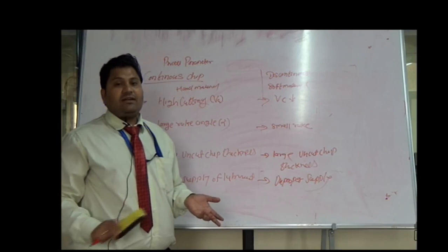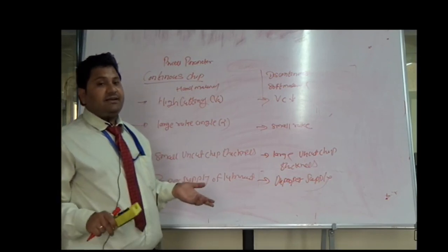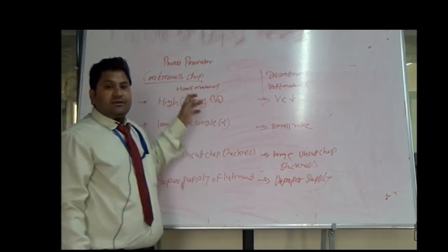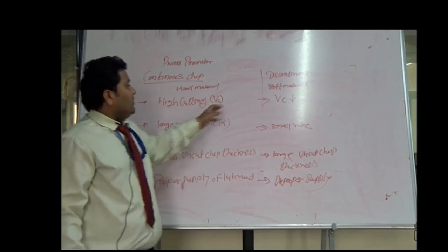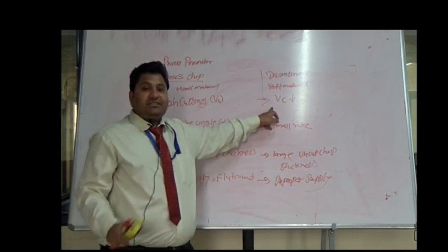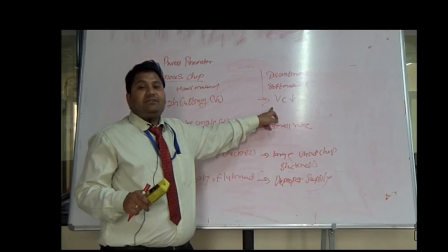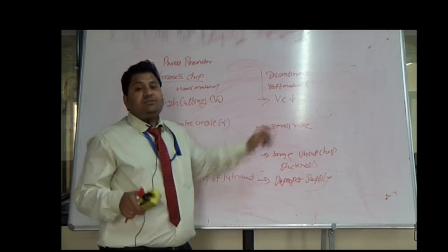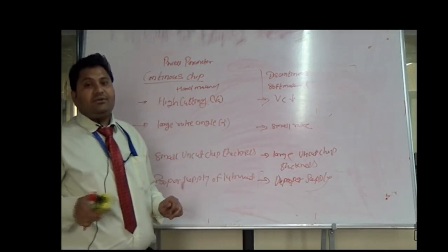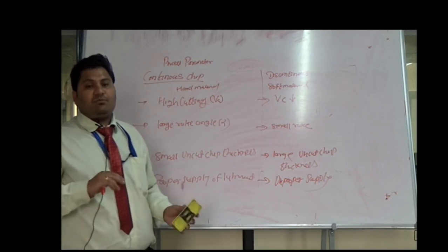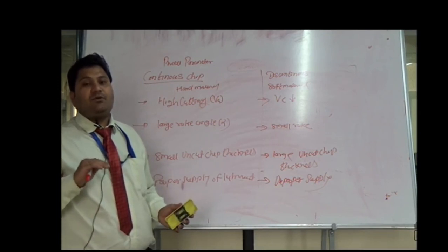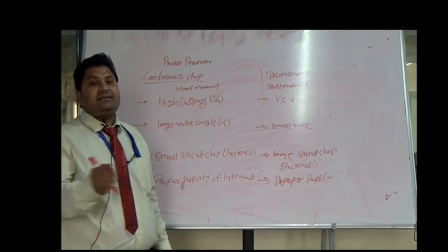It is not compulsory that only a ductile material gives continuous chips and only a brittle material gives discontinuous chips. It depends on which process parameters you use during machining. If you maintain proper process parameters, you get the desired shapes.